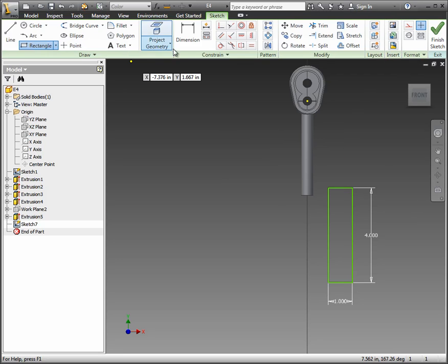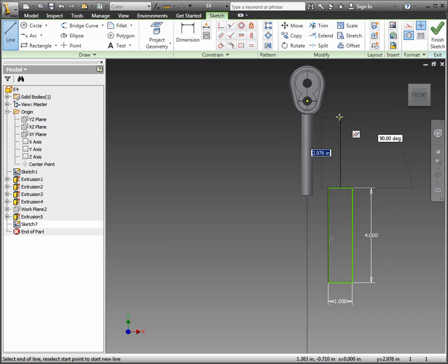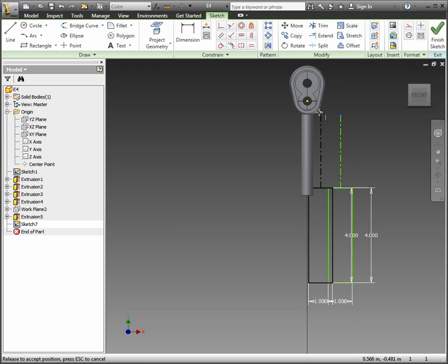So what I want to do next here is we're going to go to the line tool and find center line. Select the center line, then go ahead and glide up here, and what you're finding here is a midpoint relationship with that rectangle. Click on that midpoint relationship and just drag it up approximately 3-4 inches, and then hit escape. Now at this point we can actually grab that point after you hit escape and drag it and connect it to the origin, that little yellow dot there in the center.